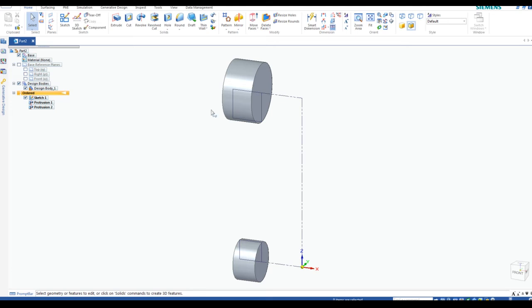Our next step is we are going to create a non-linear connection point, which is the rib itself that goes from the first boss to the second boss. To do this, we're going to use a tool called Loft. But before we do anything else, we have to set things up, as always. So we are going to create a couple of planes. We need the shape to actually be perpendicular to the axis that we have.